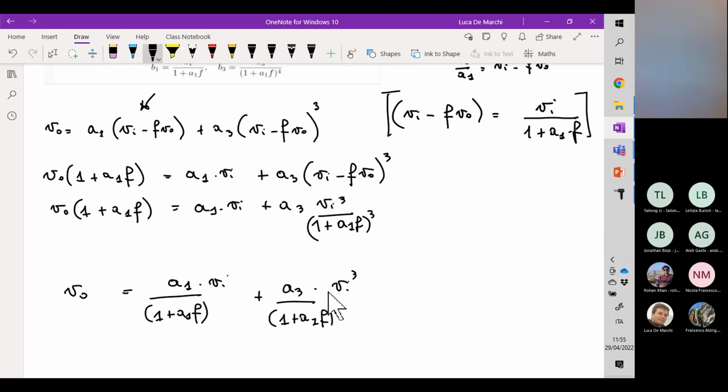And what is interesting is also that if you remember the Nyquist criterion, what we can do is find the value of omega which equates the amplitude of the loop gain to 1. And by looking at this graph, 1 obviously corresponds to 0 dB.